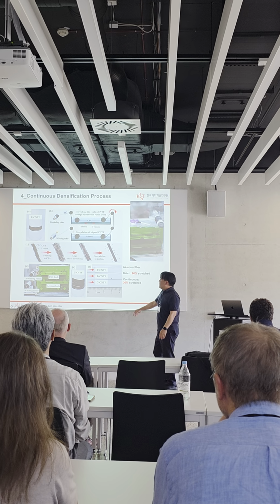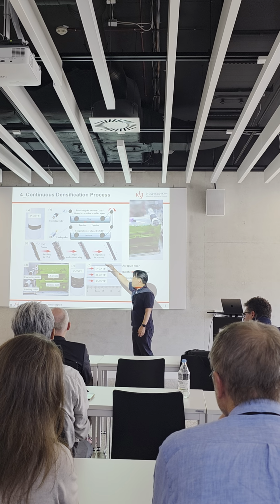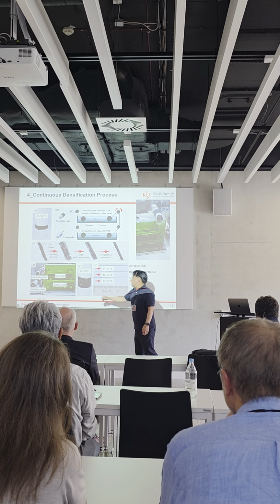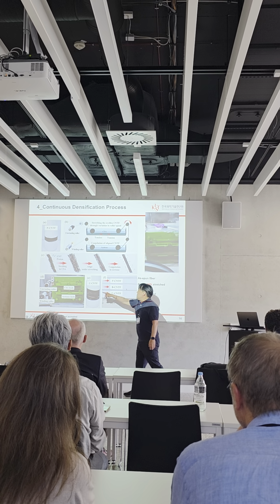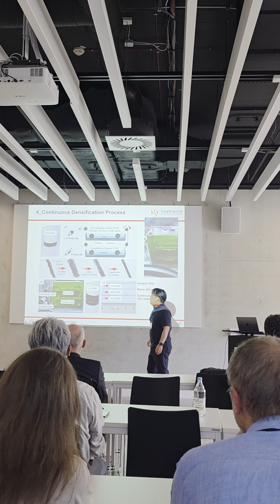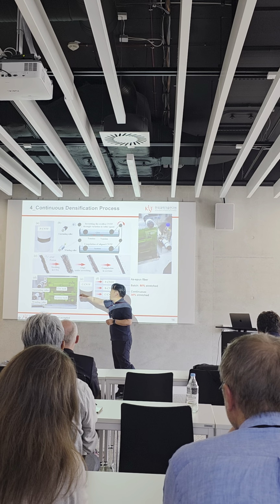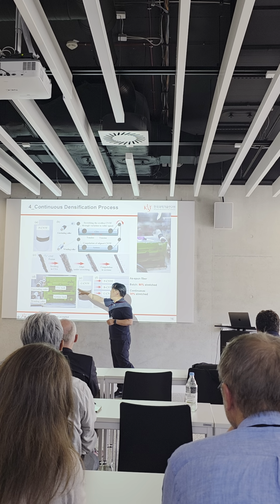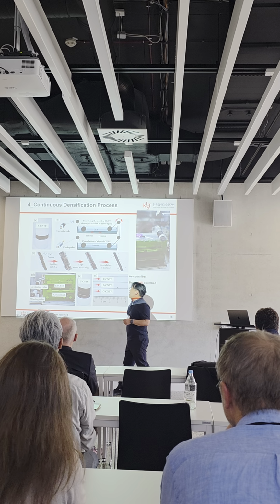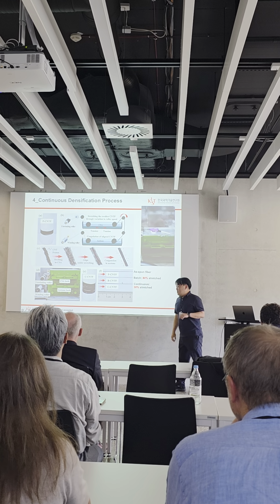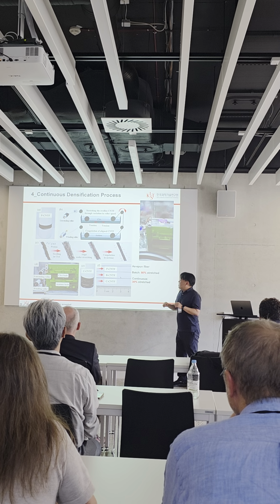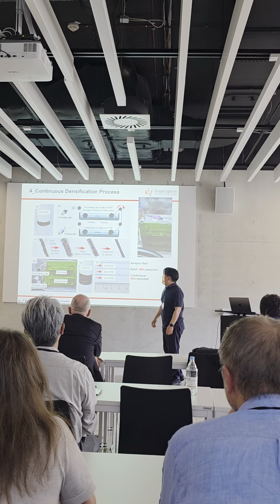We put the CSA bath on top, then there's the acetone bath, and some rollers. We set a different roller speed from the first roller to the second roller, so we can adjust the stretching ratio.